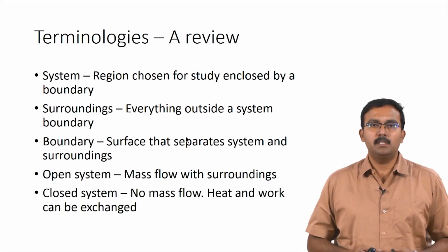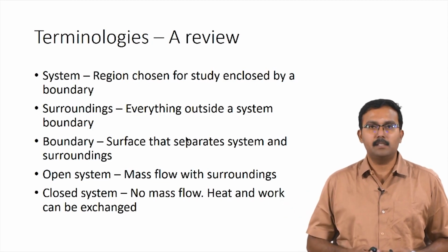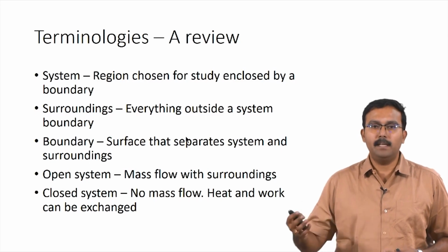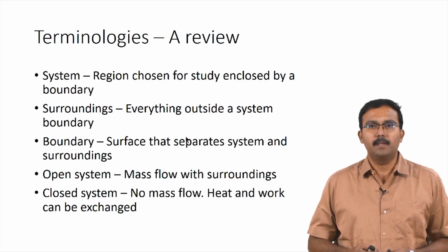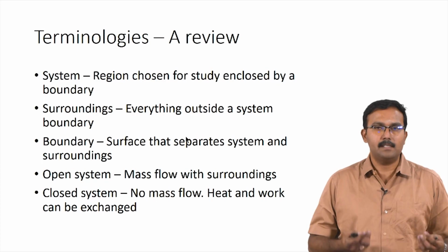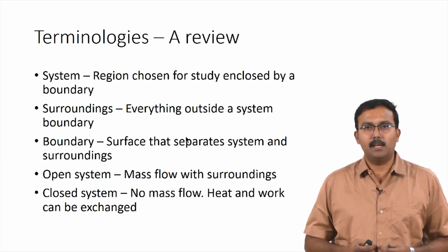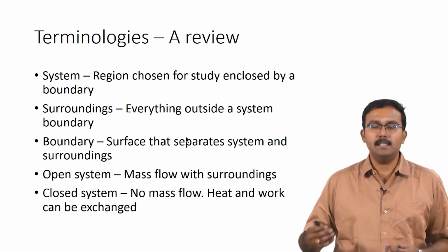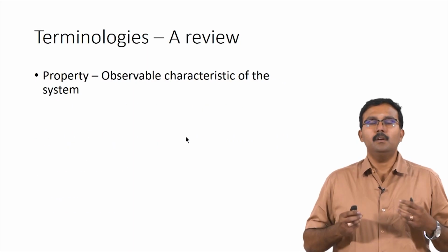You can have closed systems which have no mass exchange between the system and the surroundings. However, heat and work can actually be transferred between the system and its surroundings for a closed system. Hence, when we performed material balance calculations, we would not have looked at closed systems. But now that we are going to look at energy balance calculations, we have to consider closed systems also, because energy is being transferred between the system and its surroundings in a closed system.